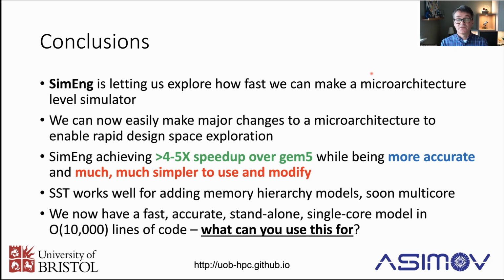So we can now model all of that, and most of that's captured inside our load store units. Our load store models have had a lot of work on them over the years. And each time we had support for a new core, so when we went from ThunderX2 to A64FX and now to V1, we're always looking at that, to see what new things they support that we haven't had before. But we've seen most things now that load store units can do in supporting a complicated memory hierarchy. And now with SST, we can support quite complicated memory hierarchies as well, where you've got all the different caches all doing different things at the same time.